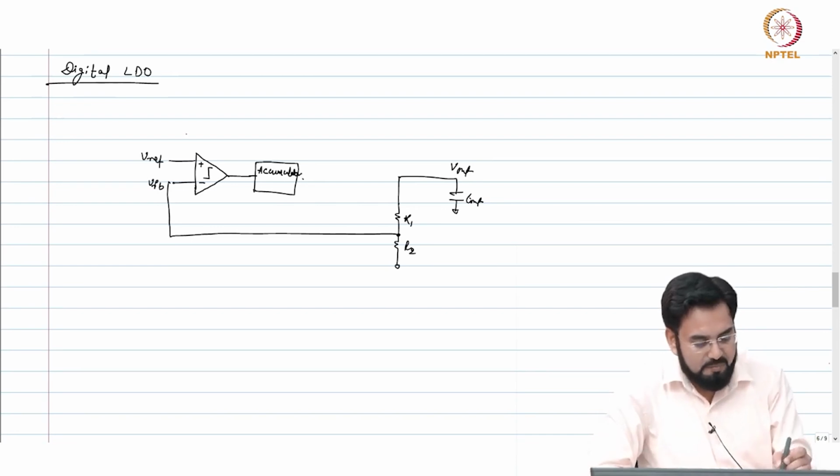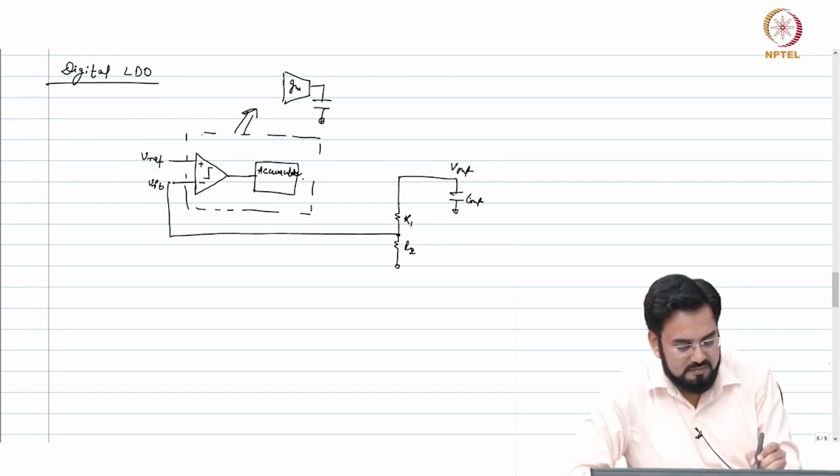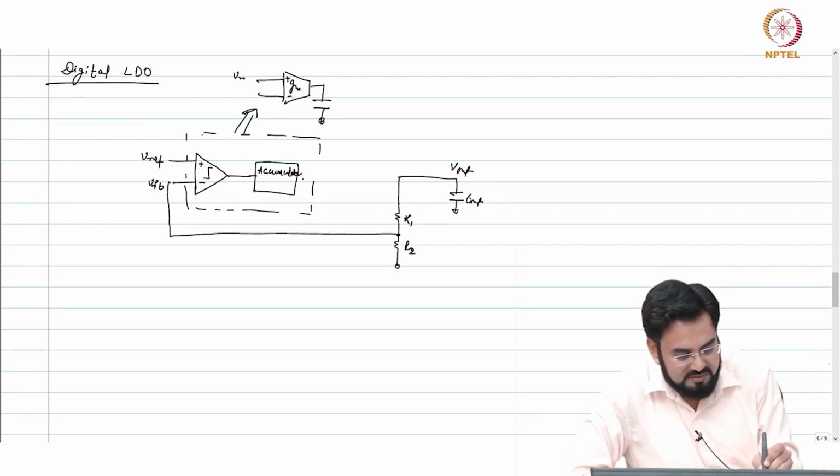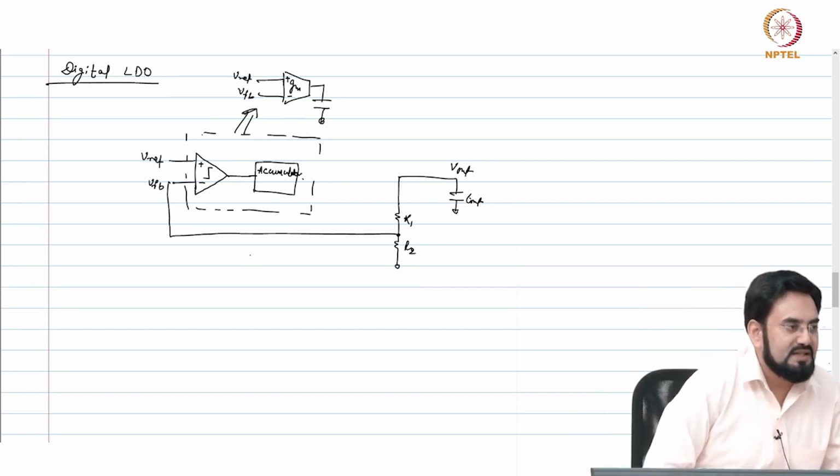Basically this comparator combined with accumulator is equivalent to an analog integrator with limited resolution. So, this is behaving like an integrator.